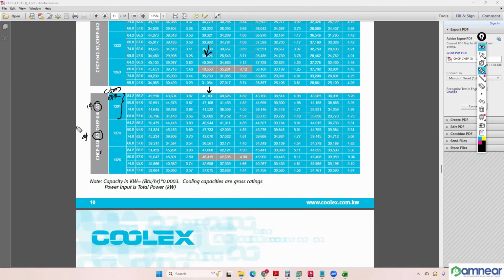Normally, the indoor equipment, the ductable unit that is coming inside, will be having a fan only. So it will not be having complex electrical equipment. Most of the time that will come to less than 500 watts only. So it means single phase only it will come. Okay, so this is medium speed and this is high speed. Anyhow, for the hot kitchen, sound is not a problem.